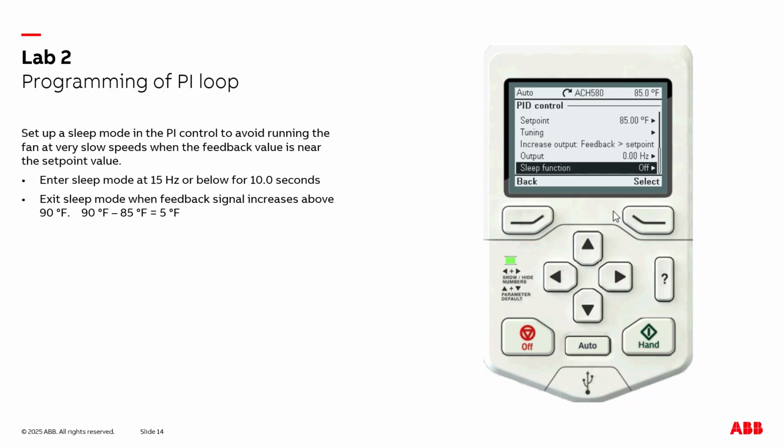We also need to set up the drive to wake up if the discharge temperature of the water from the tower reaches 90 degrees Fahrenheit. Now, if you want to pause the video here and attempt to do this on your own, do so now, and then unpause it, and I'll show you how to do it.